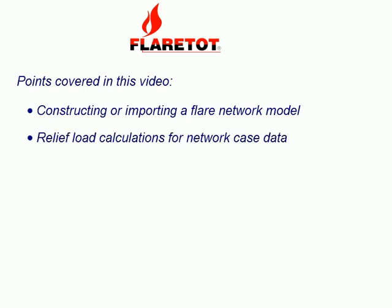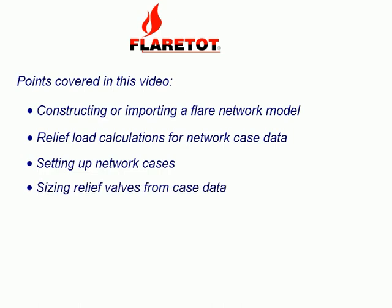Also, how to use the relief load calculations to create network case data for pipe network or relief device sizing. Then, how to set up the network cases to define the Flare network loading for design or rating. Finally, how to size relief valves from the case data already entered for the network.